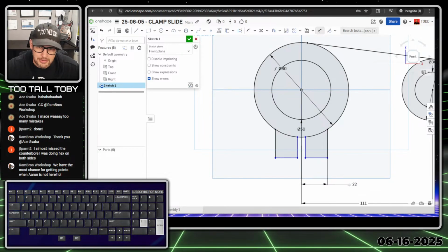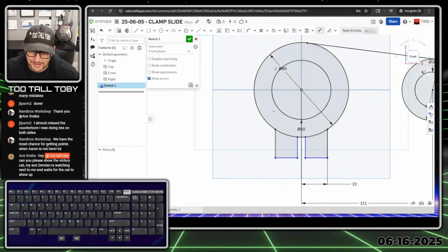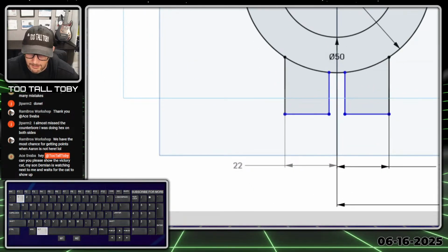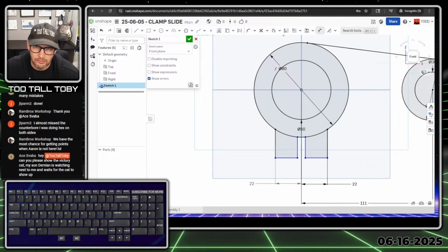So this is going to be 22 in that direction, and then if I wanted to confirm, I could click this plane and then pick on this line here and just make a driven dimension. Whenever you have an over-defined dimension there, if you just press enter, it'll show up as driven. It didn't work that time because I typed by accident. Let me just do that again. So from here to here, drop that dimension and then enter, and see it automatically becomes driven. It's a slightly lighter shade of gray. So it automatically becomes driven there because it would be over constrained.